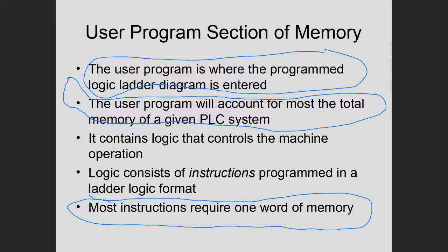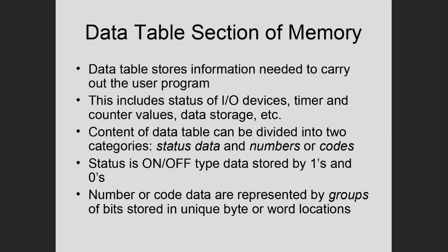Well, a single switch only requires 1 bit, but we'll get into more complicated output devices like counters and timers, and they actually require at least 1 word or more. So you end up using a lot of those cells in your memory. So the user program section is where your program is, and that accounts for most of memory usage.